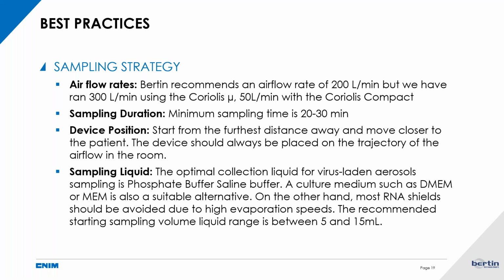The duration of the sampling depends also on the conditions where you are sampling, the size of the room. There are so many factors. So here we are only pointing out some tips if you are new in using the Coriolis, and if you want to have an approach to better collect these molecules or virus. Okay, so we are suggesting a minimum sampling of 20-30 minutes. If you don't have long-time monitoring for the Coriolis Micro, you can make 2 or 3 runs straight.